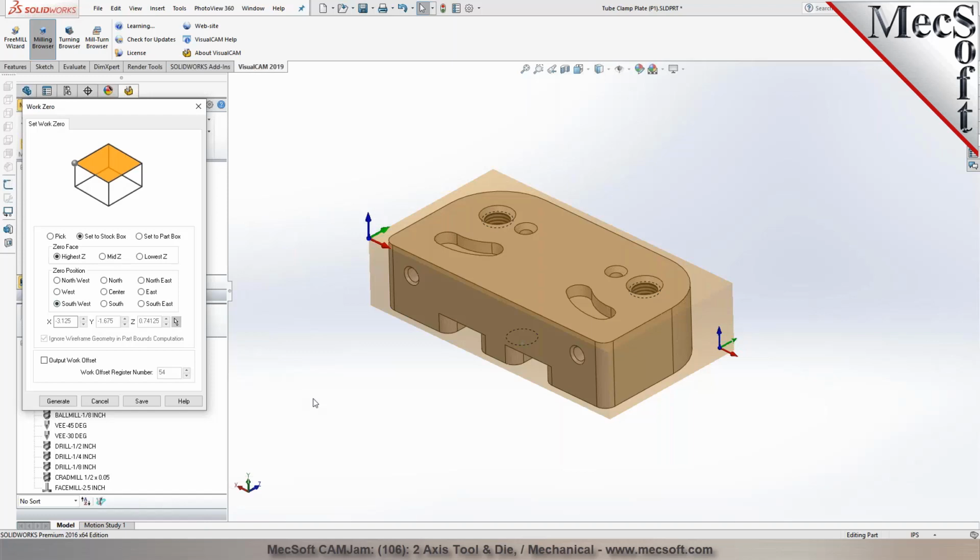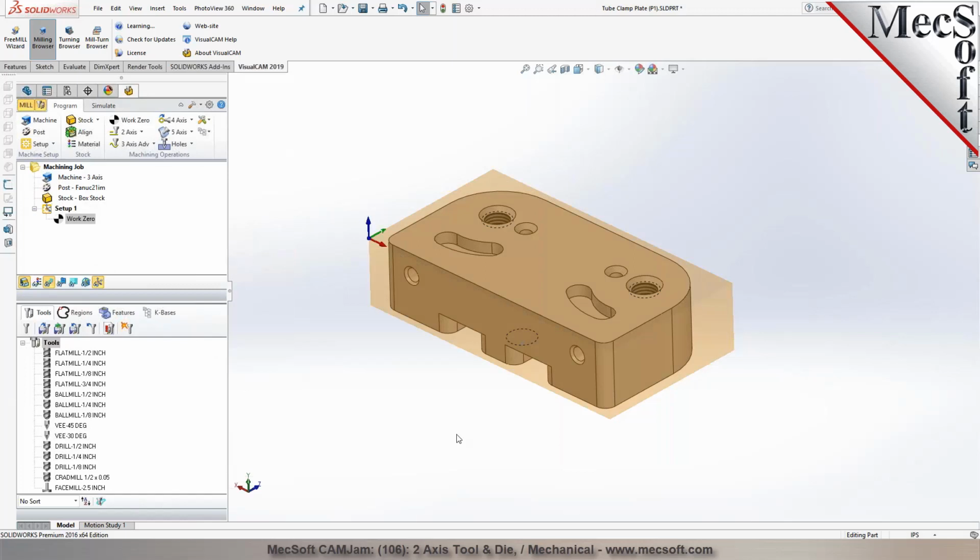This would be where you place them in a workpiece and then bring the tool to touch down to establish your G54, your work coordinate offset. That looks fine to me. And then we can also select the work offset, and if you want to output a G54, you can specify 54, and then the prefix will be added in the posted output file. So there's the location of a work coordinate origin.